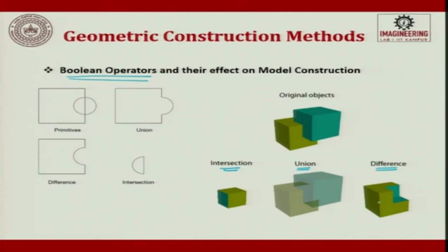What this means is, rather than drawing a component fully from scratch, you use these solid model primitives and smartly use Boolean operations to get the profile or feature you want. For example, if you wanted to generate an ellipse, all you have to do is pull a plane option in the model, pull a cone option and place it at some place, and say A intersection or A union, whatever you define, and the profile that gets generated is going to be an ellipse.